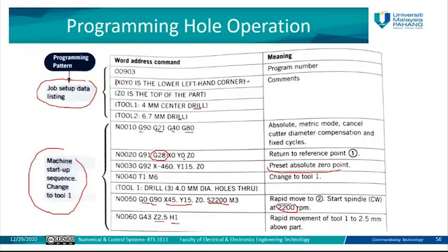But if you want to write a good program to be used with a real CNC machine, all the programs that we have in the slides are applicable to a real CNC machine. They may not run on the simulators. Any of the simulators may not run this G code, because the dimensions of the machine in the simulator are different.